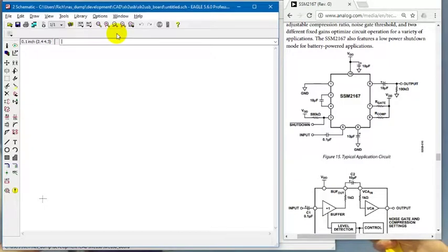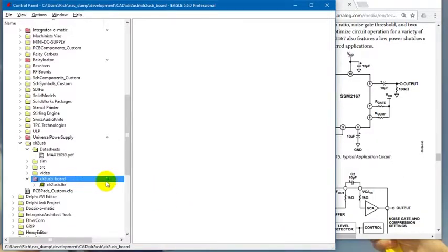When you start out with the schematic editor, you end up with a big blank sheet of nothing. So one of the first things we want to do is add our title block to it. We spent a little time copying and pasting that in a previous episode. In order to add something from a library, we first have to make sure that library is selected. So in the Eagle control panel, first make sure your project is selected with a green dot, so you're working with the current project, and secondly, that the library we created before is selected with a green dot.